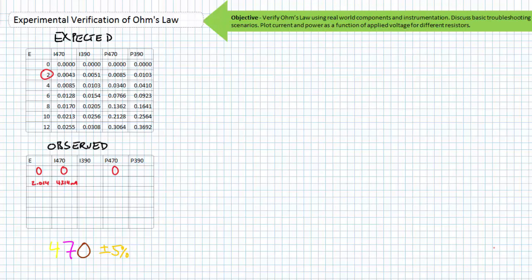Notice by continually employing the function, leads, range, and placement checklist every time we've made a measurement, we never shorted anything out, opened anything up, or operated outside the measurable range of the meter in either voltmeter or ammeter mode. I'm hoping this proves something I've been saying all along. Imagine how well lab will go if you know what you're doing. Your first lab may not go as well as this.